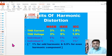However, generally IEEE standards are taken into consideration and a THD of 5% is usually allowed. Now this depends on the ISC by IL ratio, which we are going to study later. So it is the ISC by IL ratio which will decide what percent of harmonics is allowed. So 5% is taken as a notional figure, but it is the ISC by IL ratio that decides the percentage.